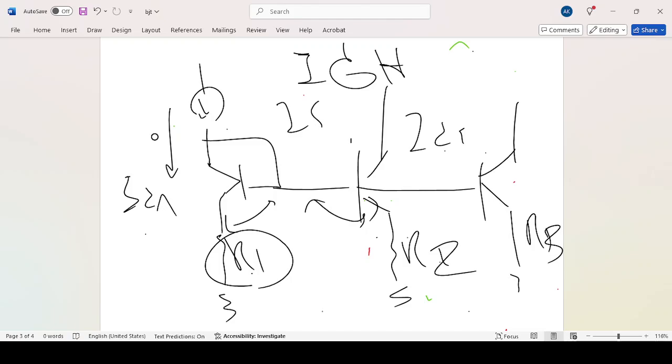Also, I hope I can find a tutorial that I had about how to simulate BJTs in SPICE, in HSPICE, without using a PDK, just defining everything, like the small signal models, even the parasitics, in an HSPICE file, and just simulate your desired circuit, just for a start, not for design, maybe for your homework, or if you have an idea, using just a non-real model, which is not a model actually, it is a small signal configuration that you define, that could help you to understand BJT behavior and even the parasitic effects more deeply.